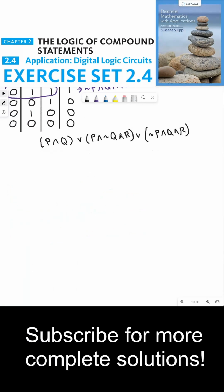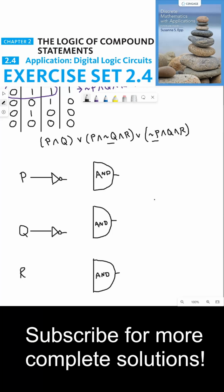So now that we have the Boolean expression that represents our circuit, we can build the circuit. So we're going to have P, Q, and R. Now at some point we're going to need not Q and not P, so let's negate P and Q first. Okay, so we're going to have 3 AND gates for each of these very specific situations. And then after we build these AND gates, we're going to need an OR gate to combine all 3 of these expressions that we build.